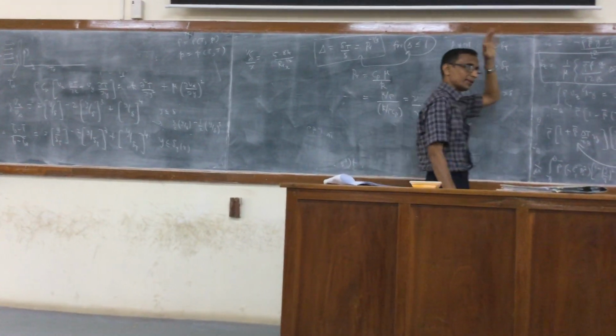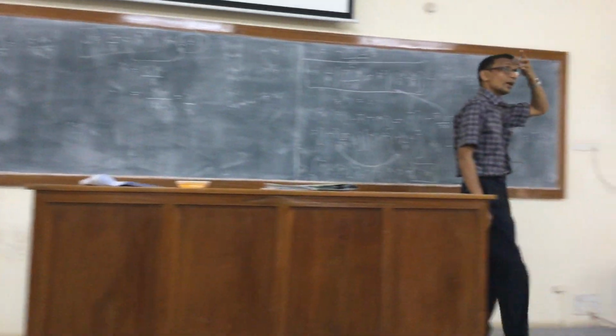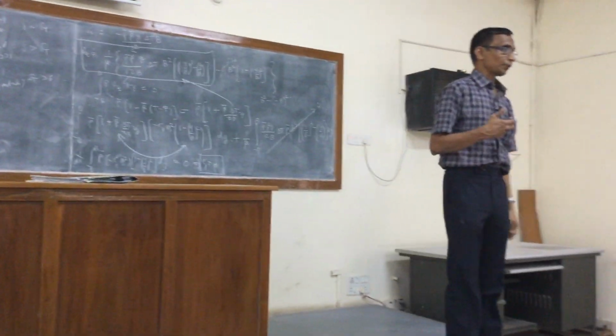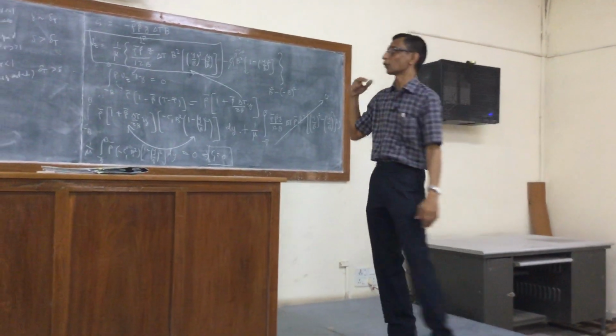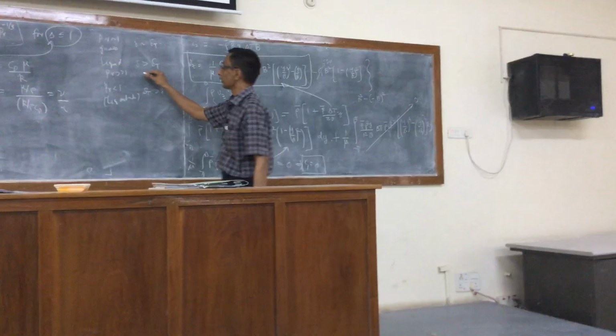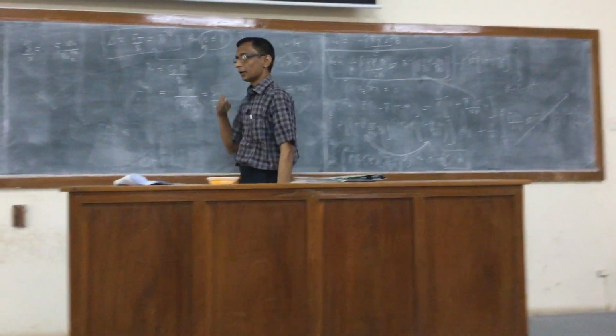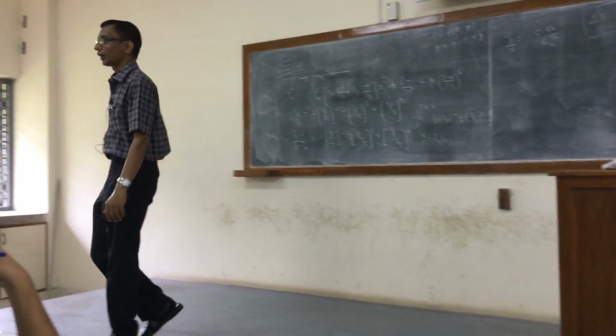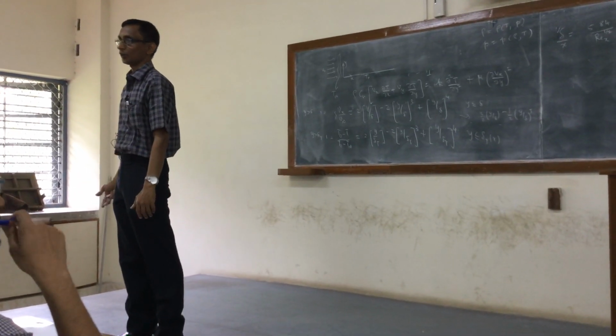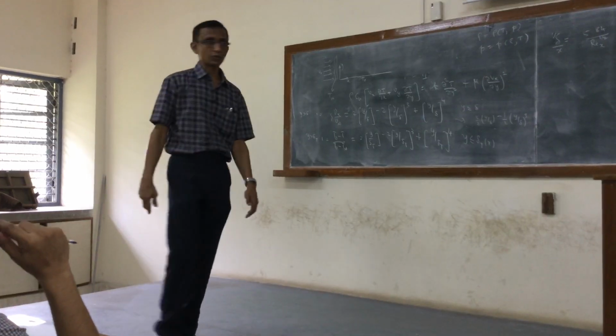So when you say that the hydrodynamic boundary layer extends far into the liquid as compared to the thermal boundary layer, what we are effectively saying is that the diffusion of vorticity is much more efficient in the case of liquids as compared to the thermal diffusion.